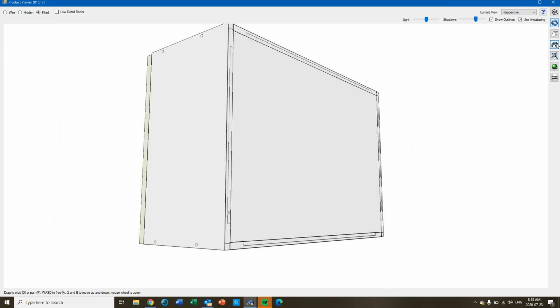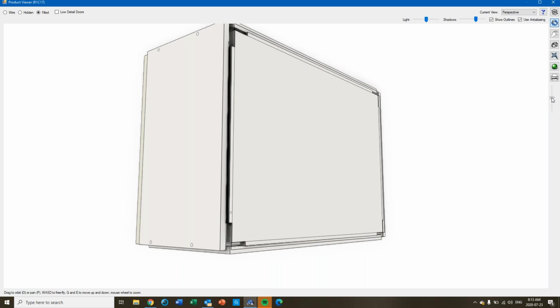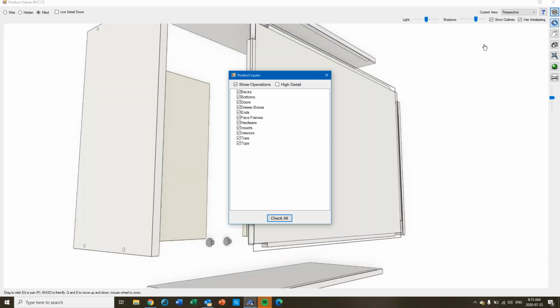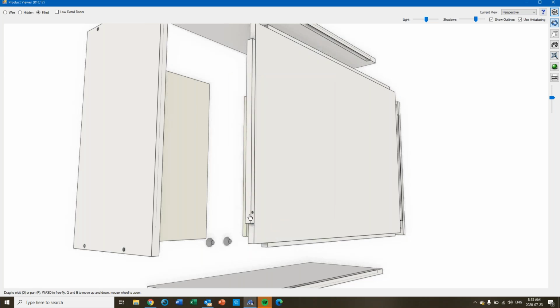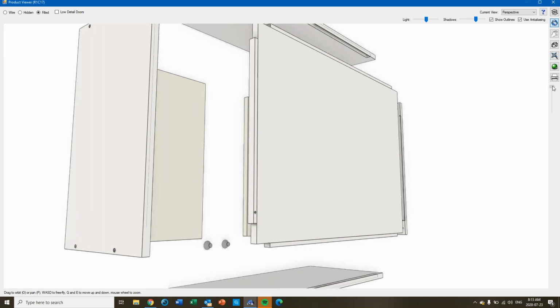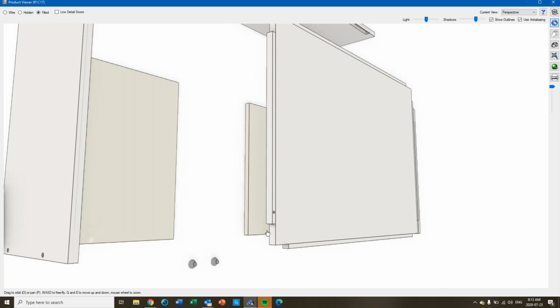So if you look, I'm gonna do an exploded view. You just have it, it's not logically set up right. If you machine it, do you see that skim of a line? But I never machined that. No, because it's at 0. It is gonna machine that. If you actually watch your machine, the tool goes across your material. It might not cut in. It might not even break the paper, but it is going across your material and machining that.